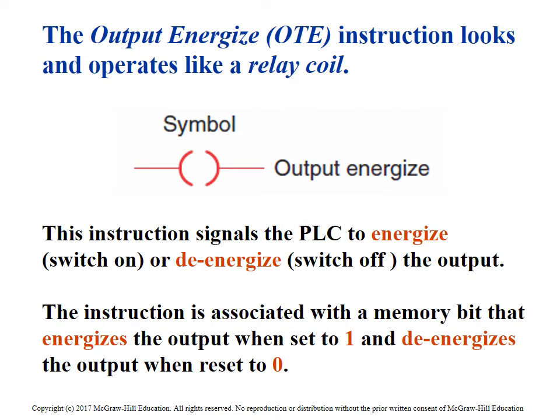OTE. OTE is output energize. Think of it that way, okay? When you see OTE, that is the output energize. That means that's the device. This is the command that's going to turn on the output in the PLC. So we need to get all the signals in front of this guy turned on, so this guy will turn on. That's the goal.